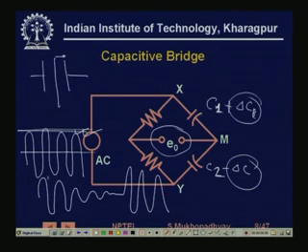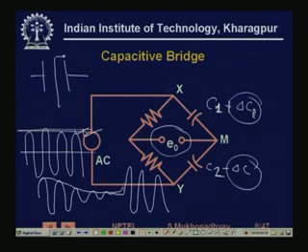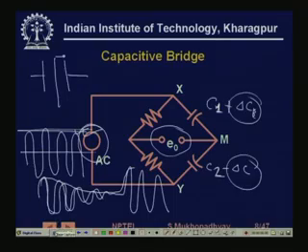So if we have to get the actual signal out, then we have to track this variation of the amplitude and reject this sinusoidal variation, which is purely due to the excitation source. We will have to reject it, right. We will see in this lesson towards the end how that is rejected. Apart from this, the bridge functions exactly like a resistive bridge.